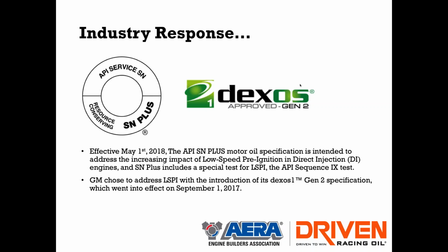And that's the key thing to keep in mind: when you're looking for engine oils for direct injection engines, the worst thing to do is to go put in some diesel oil that has a very high detergent package. I don't care what it's done in other engines in the past. DI engines should not be running diesel oils. They need to be running oils designed for them, and they need to be running oils that meet this kind of spec or have something on them that says, hey, this was made for a DI engine and it's designed for that application.